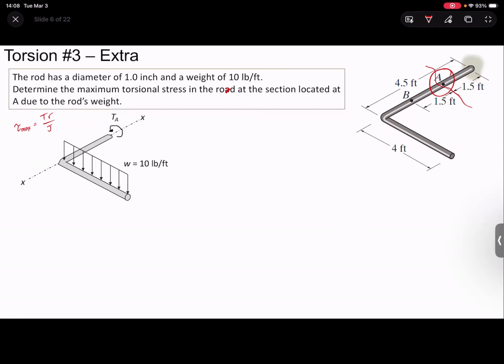Now, technically there's a self weight here, right? But this self weight shown in red that I just drew is acting on the centroid of the axis that we care about. So remember, a torque is a force times a distance, or a force offset from the point. So the self weight shown in red is acting at a distance of 0. So there's no torque applied from this.